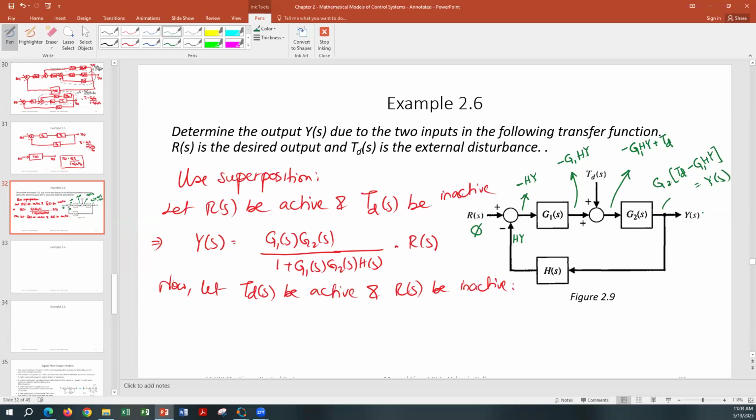The first summing point is basically 0 minus HY. So it's just the signal being subtracted that is going. It's acting as an inverting amplifier simply. R is not there, but this amplifier becomes an inverting amplifier. Take the HY signal and invert it, shift the phase 180 degrees. So that summing amplifier becomes pretty much an inverting amplifier. The nature of a summing amplifier is to invert.